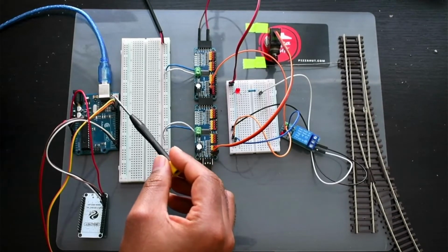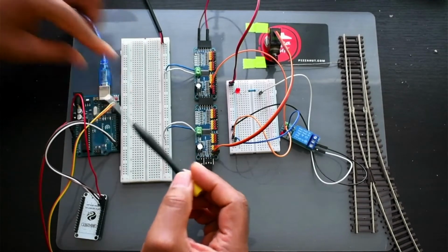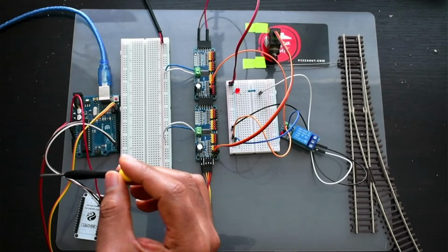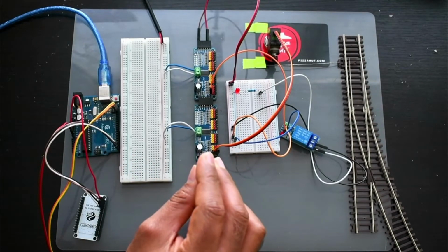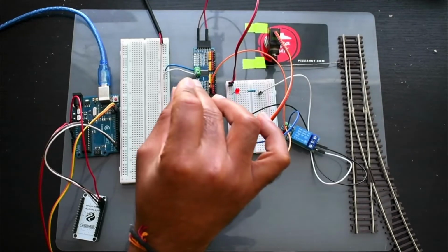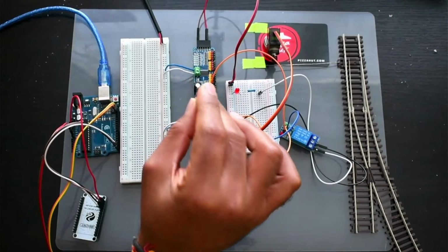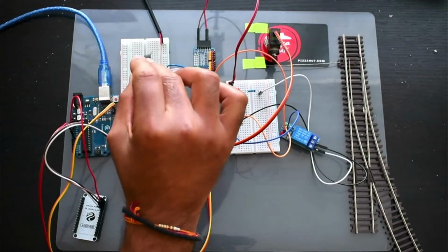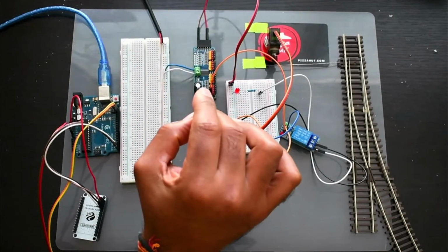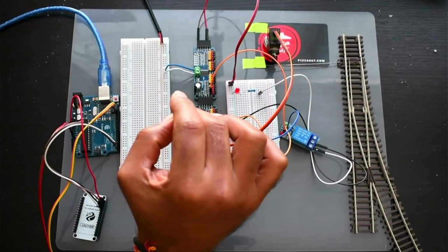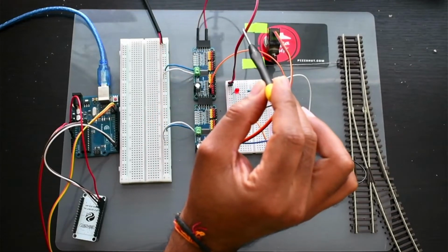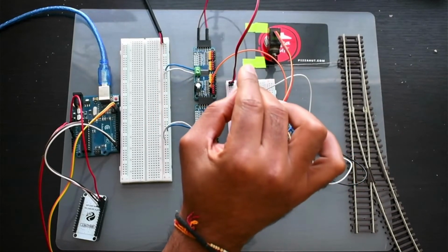And this yellow one and orange one are the SDA and SCL lines, and this brown and red one is 5 volt and GND, VCC and GND, which is going to board number 1 here for GND, VCC and the SDA and SCL lines. And then board number 2 is snapped to the back side of the first board. And from here, this is an external 5 volt power supply which is going to the second board as well as the first board. White one is VCC and blue one is GND wire. And from the end of the second board, you can see there is a 5 volt VCC and GND coming to this breadboard.